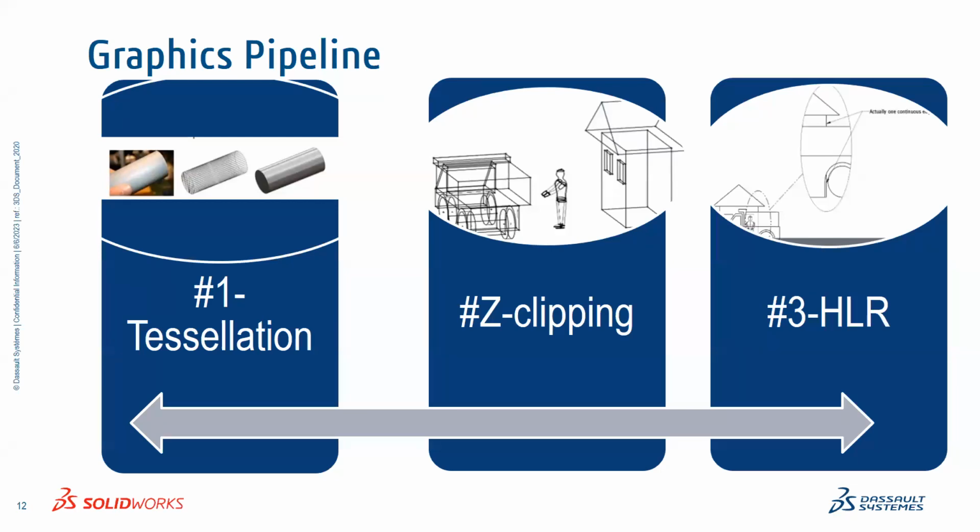Whenever I open or recheck that option and click it, it takes too much time, because it also has a lot of triangles or faces we want to see. There is precision HLR, which is highly loaded graphics. If someone by mistake clicks on that high performance HLR, it kills your graphics card. It doesn't matter which graphics card you have.